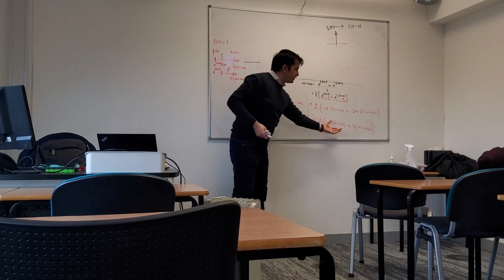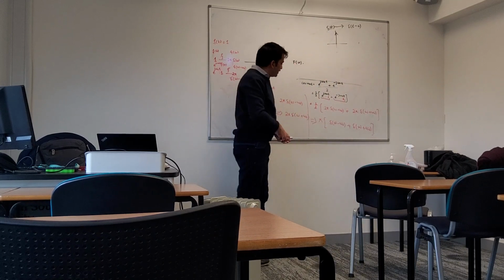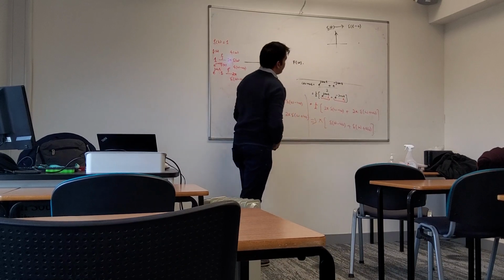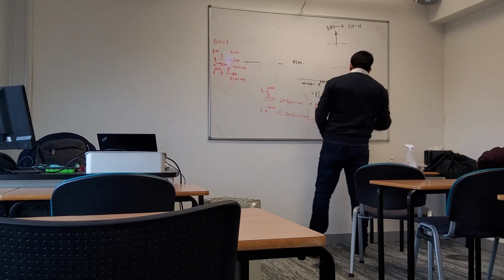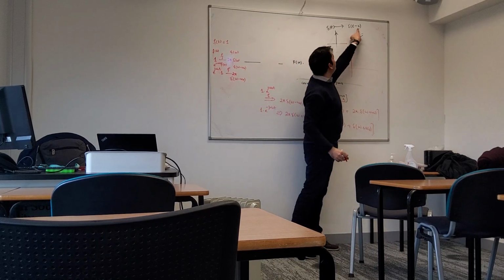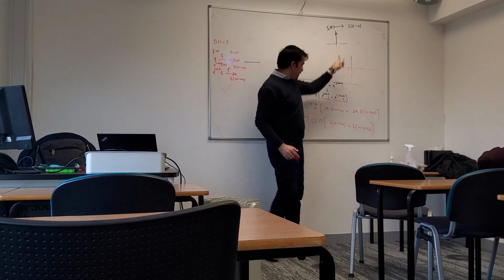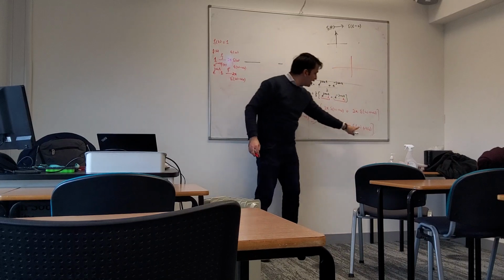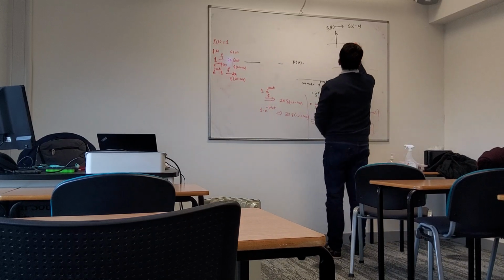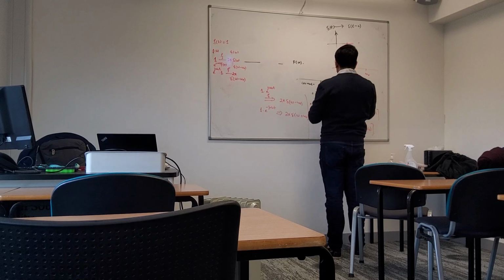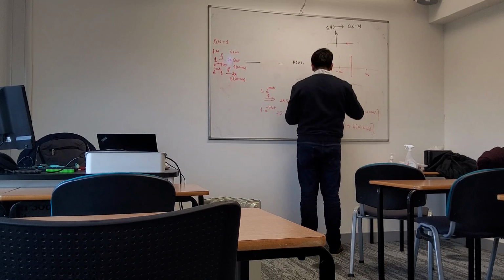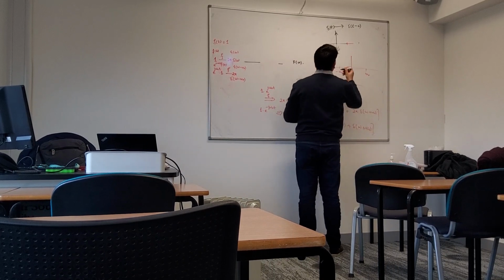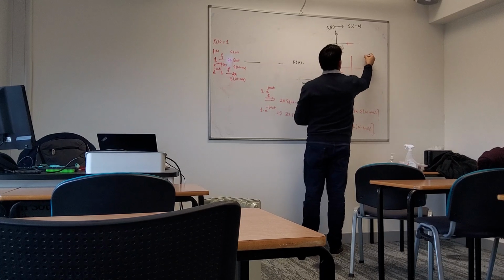If I relate it with the similar thing, for the Fourier transform of cosine, at 0 I have a pulse. In this you can see that you have omega naught and omega. So omega naught would be here and minus omega naught would be here. So I have two pulses, one here and one here.